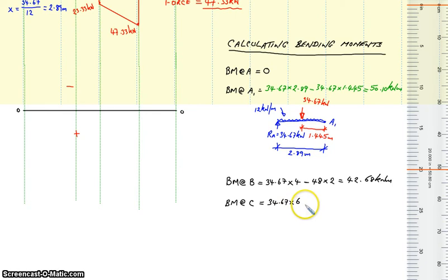That's the only clockwise moment we have, so again I'm putting in a negative sign to look at anti-clockwise. And we have the 10 kilonewton point load coming into play there, and it is 2 meters over from point C, so it's minus 10 times 2. We also have the converted UDL to the left of C, which is all of that UDL of 6 meters long and 12 kilonewtons per meter. So again, it's going to be an anti-clockwise moment, and it's negative, and it's going to be converted into 72 kilonewtons, and that is then multiplied by half of the length of that UDL, which is 3 meters.